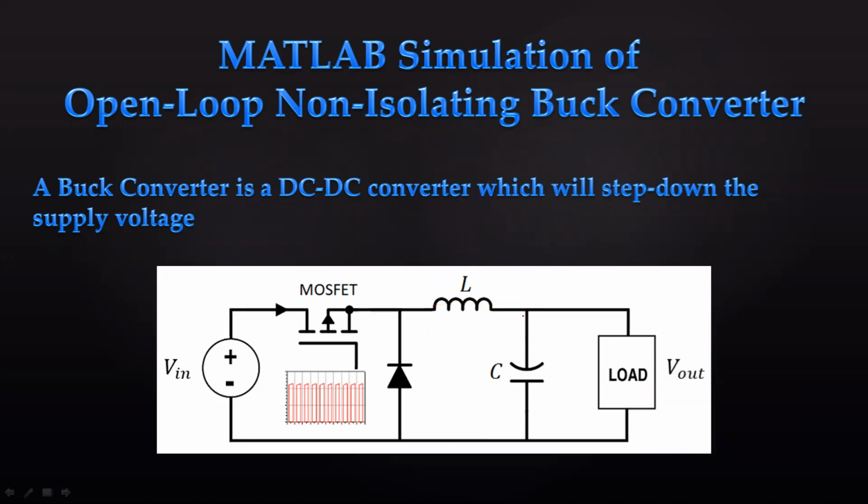Now on the second condition, what will happen? This is open circuited, so it behaves like an open switch. So current will not move in this particular loop. But now, we already charged this inductor earlier while the MOSFET was on. So now this inductor will discharge. While discharging, the polarity will change. So plus will become here and here it will be negative.